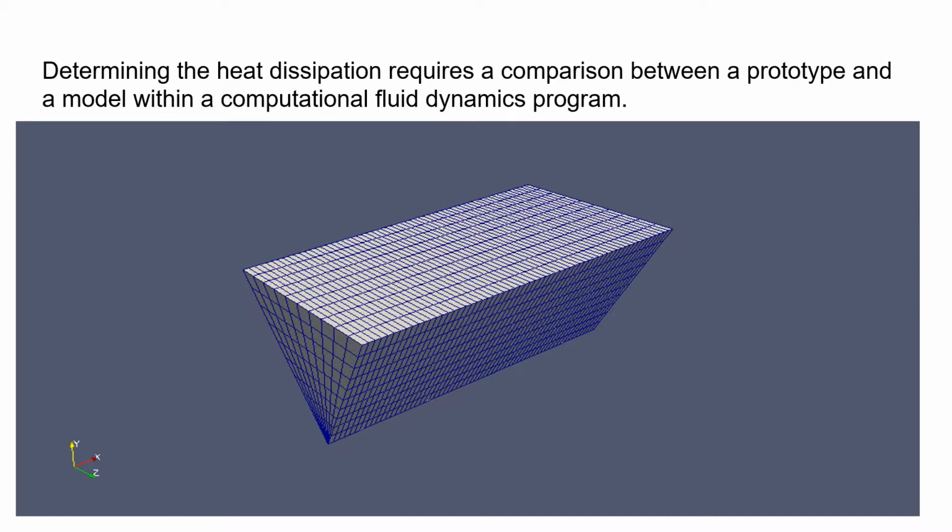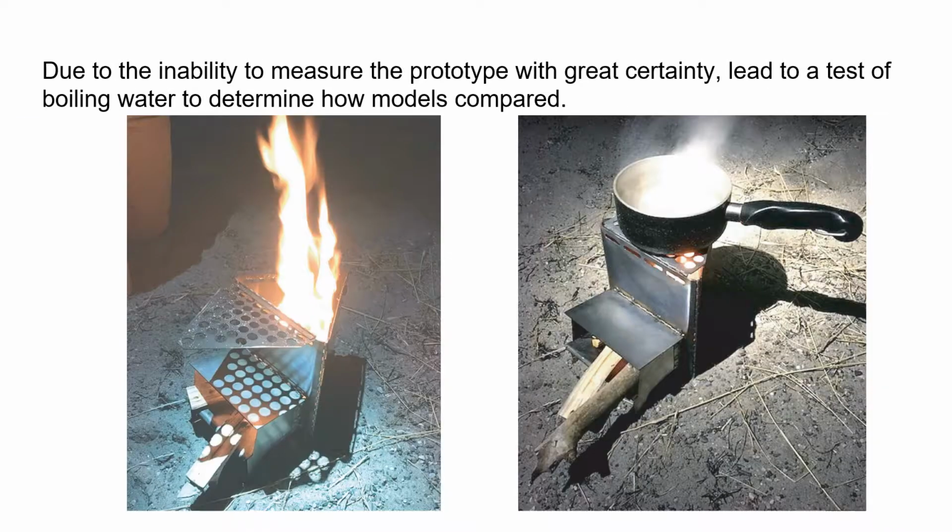In the computational fluid dynamics (CFD) model, we decided to go with an ambient temperature of 300 Kelvin. The fire itself will be around 1,000 Kelvin because the average fire burns at about that temperature. For your information, regarding the boundary conditions, we did not know how the inlet would act, if it would push some of the hot air out or in, so we left that as a zero gradient. The walls itself, we knew for a fact wouldn't change very much, so we left them as a zero gradient as well.